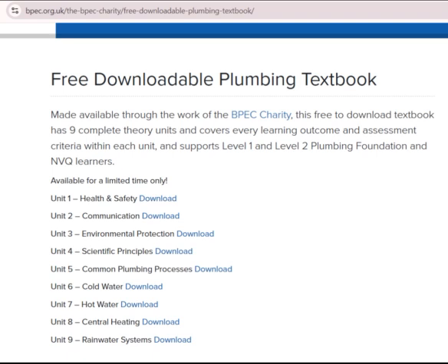AC 7.3 state the procedures for dealing with defects in central heating components and pipe work. 1. Failure of control components. Most control components use electricity. Do not attempt any repairs or replacement of motorized valves, thermostats or programmers/timer clocks. These should be checked by a qualified, experienced operative.